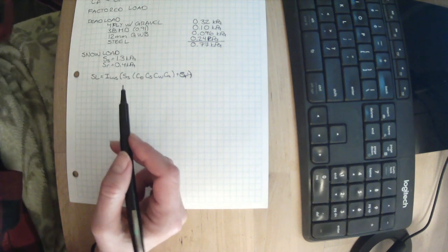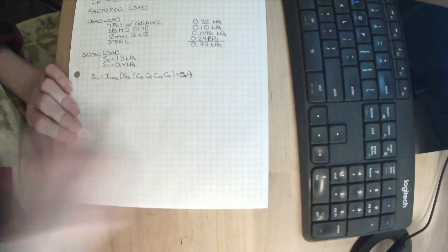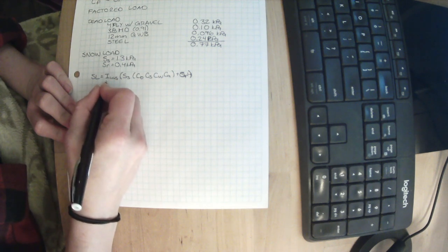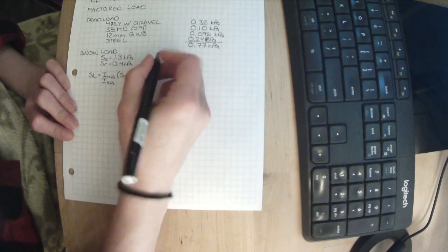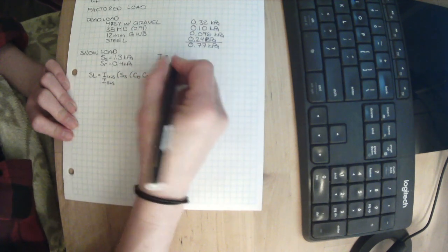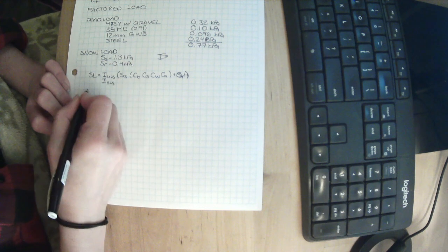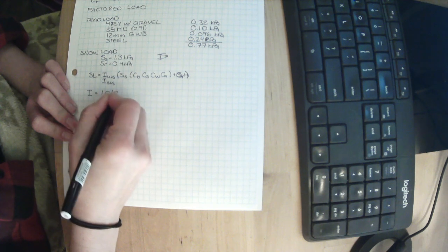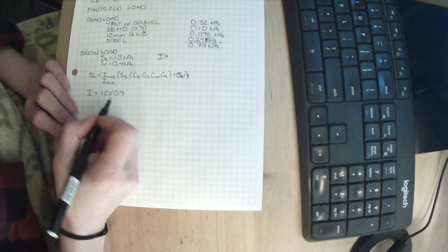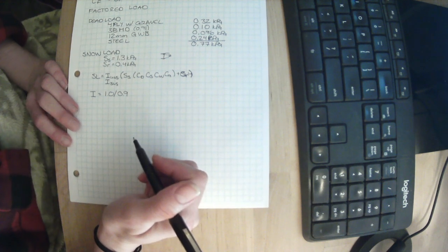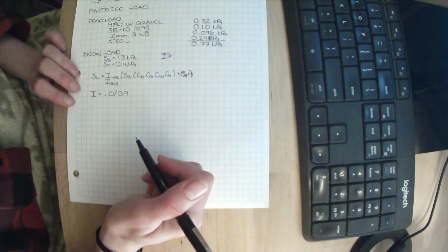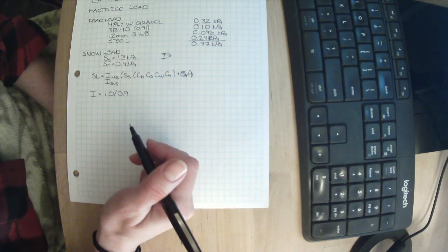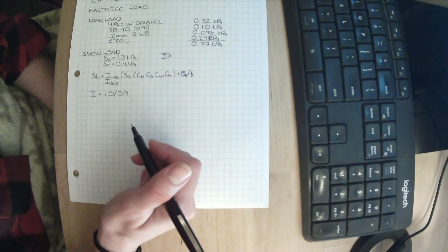We also have our serviceability case as well. So we need our I value, and we also do this for SLS. I equals 1 or 0.9, depending on if it's ULS or SLS. There was nothing in this equation that said that this was an important building in any way. So we are going to go under the assumption that it's a regular importance factor building. Unless I tell you otherwise, that's what I'd like you to assume.